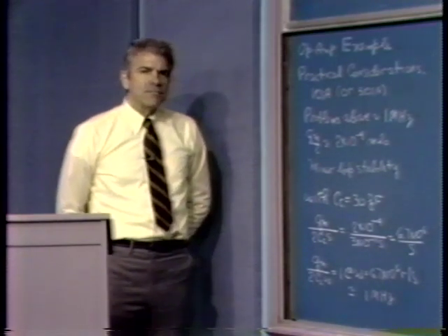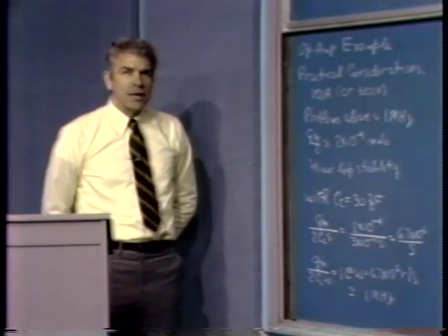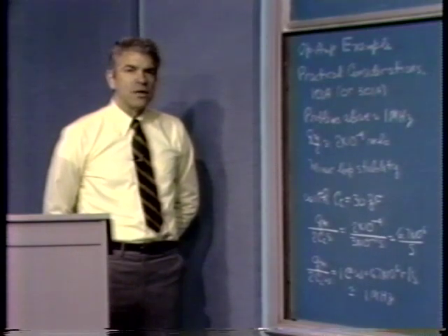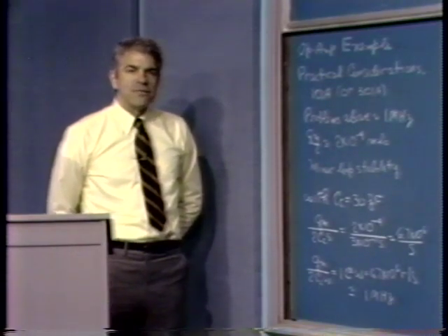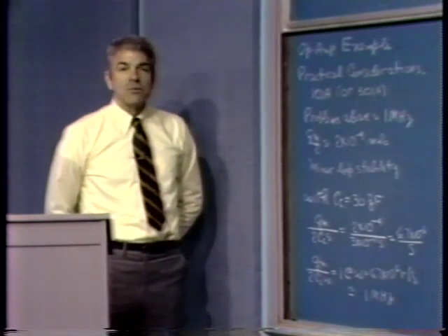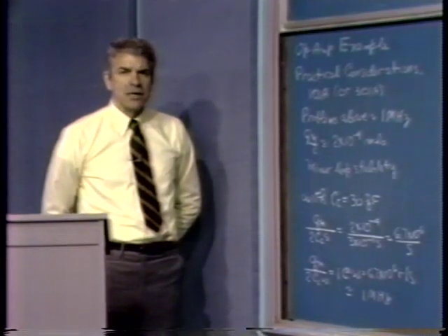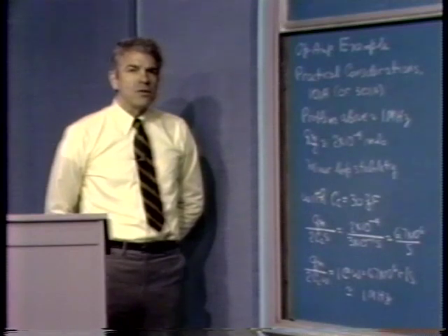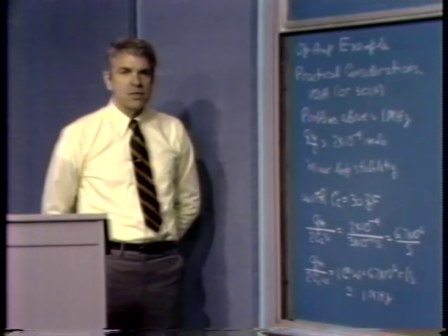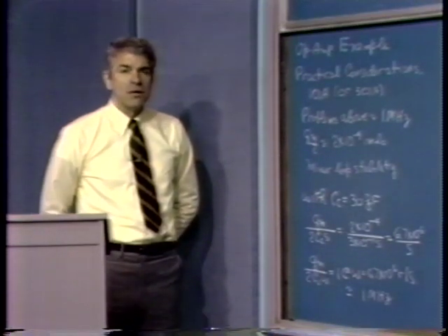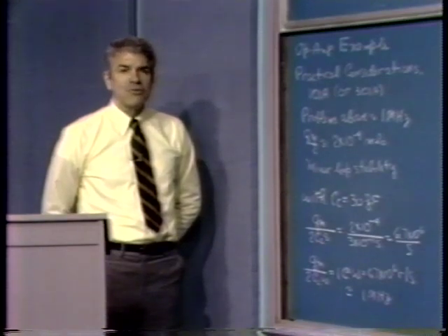A final thing that we didn't mention last time, but will become important in the session that follows this one, is that certain kinds of minor loop compensation result in stability problems associated with the minor loop itself. So we have to be careful when we do the compensation in this system, or in any other system that uses minor loop compensation, to make sure that the minor loop remains acceptably stable.